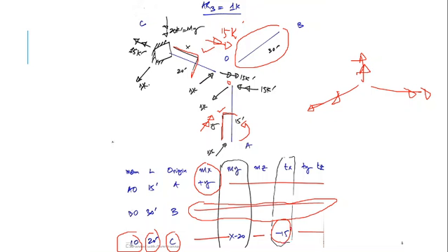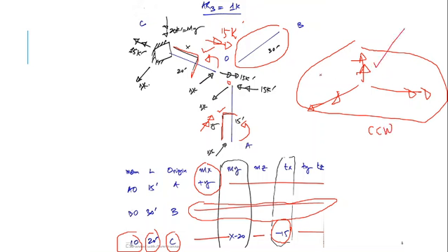Next, I have this 20 kip foot. How has it come here? Because one kip was in Z direction. This was in X, and if you move this load towards the support, it is forming an anti-clockwise moment. So I have applied a clockwise moment, because these are all counterclockwise. If this is a counterclockwise moment in Y, then this is a clockwise moment in Y, downwards.